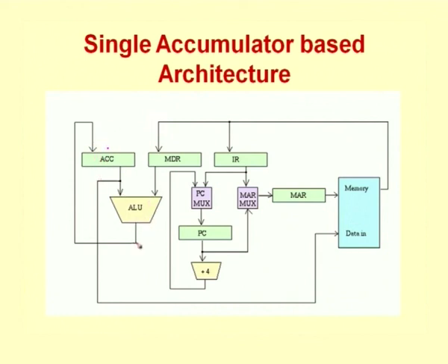All the operations are performed over here. You have to perform an operation here and then store the value back into the memory. From the accumulator you will have to store it into memory and then again bring it back from memory, and so on. You will find that the type of instructions we use in this case are a little different, which is why we said the organization will affect the type of instruction sequences that we are able to construct.